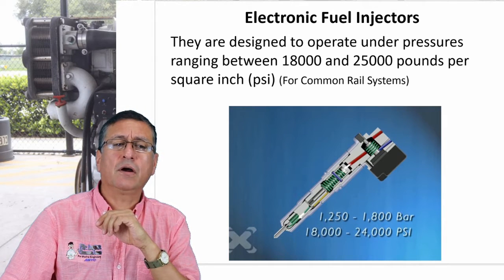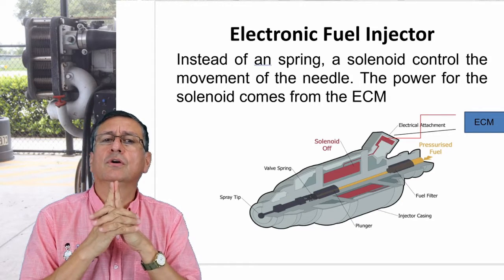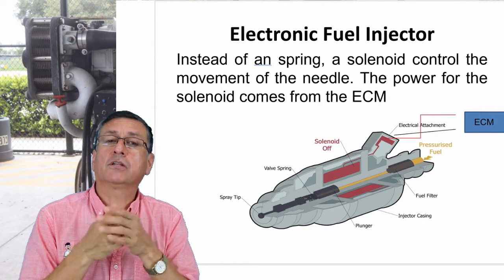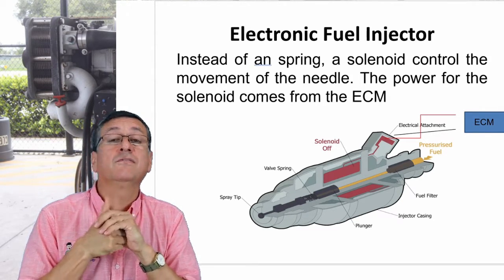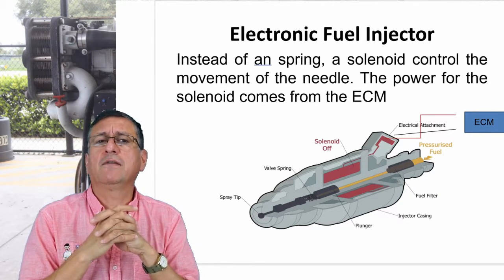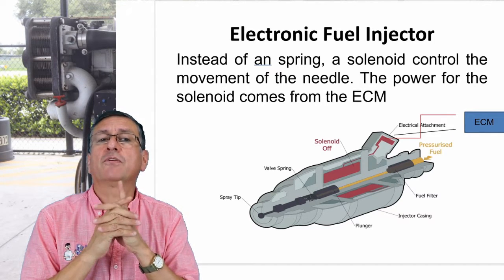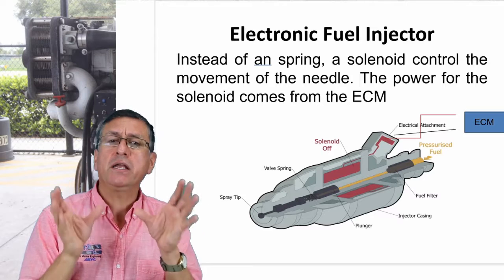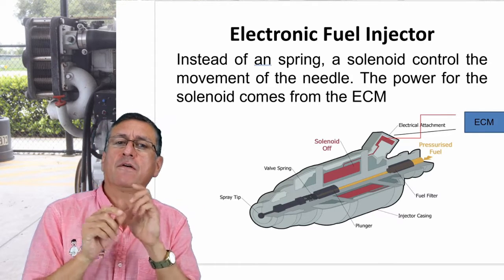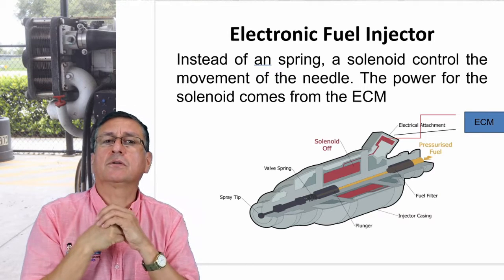Okay, my friends, right now I am going to show to you the procedure to repair those injectors. Those injectors receive the signal from the computer. Remember, the signal is in between 4.5 and 5 volts normally, and it's a DC signal coming from the computer. If you check the wiring diagram in the service manual, you can find where are the pins dedicated for that specific injector.